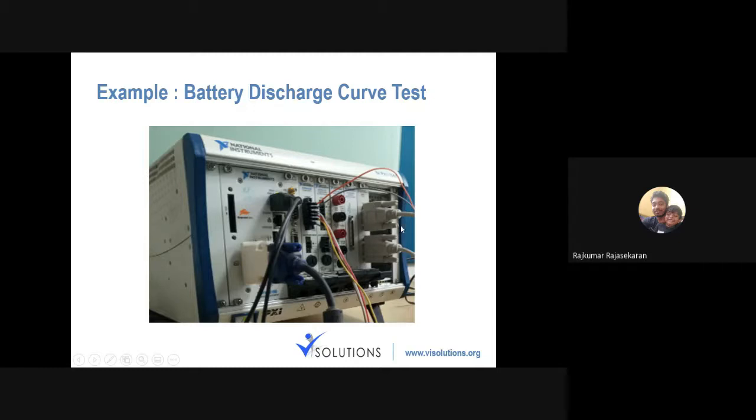And that particular battery also had a CAN communication protocol, which we need to check whether an internal component of the battery was able to make the measurement properly. Basically, we need to compare that what we are measuring is equivalent to what is being measured inside the battery, whether that is syncing or not. That test is being done.